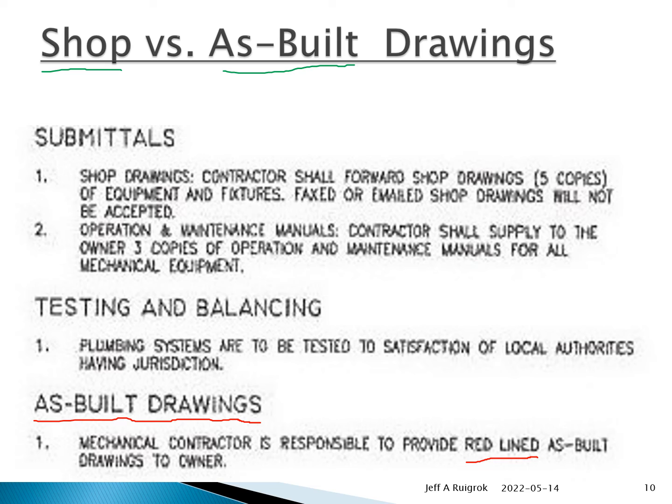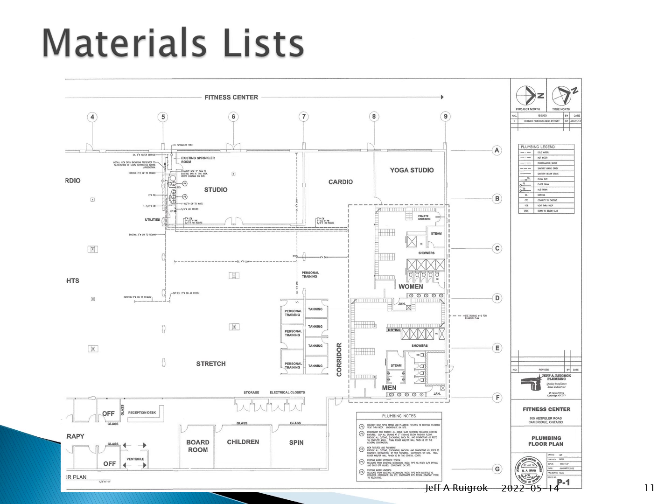The reason they're red line is because anything submitted to the city that is authentic and not just a print, at least in days of old, nowadays digitally, I don't know, but in days of old, it always had red. So if Gabor's stamp was red and the lines were red, that means it was all official stuff from the city. All right. So now you have a sense of how we interpret the architectural drawings to create shop drawings, and then the actual finished product might look a little bit different, so you have an as-built drawing.